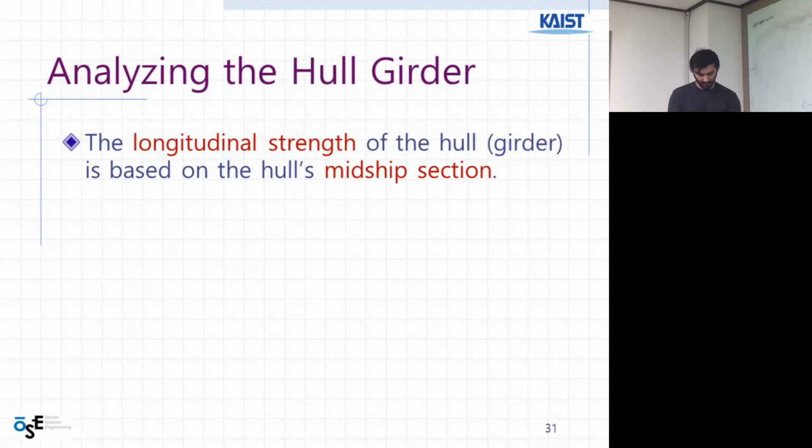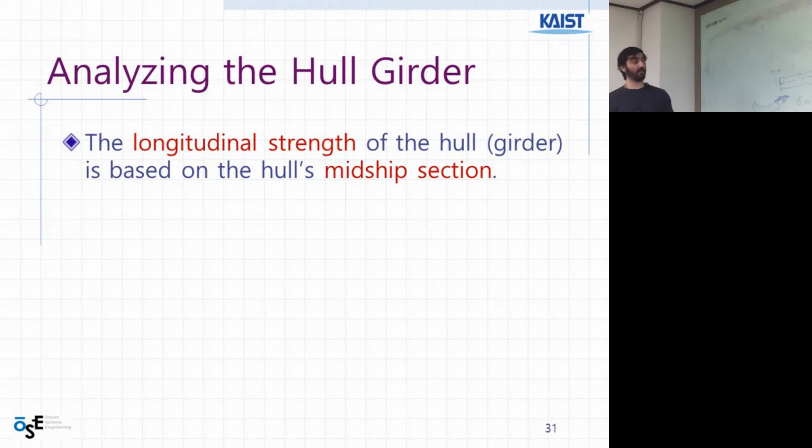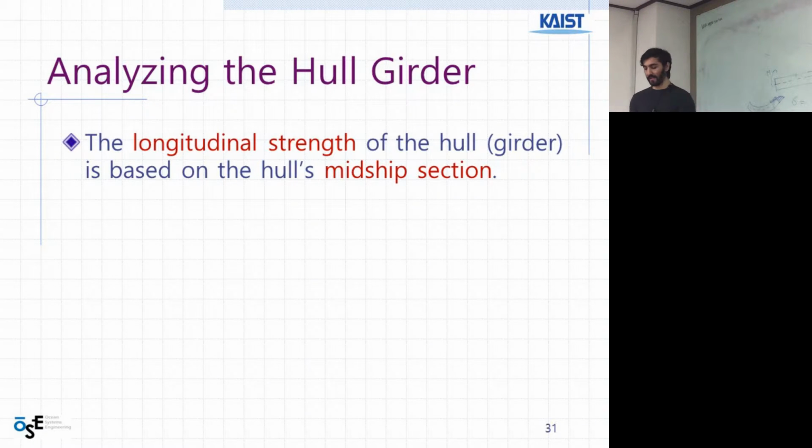A girder is a longitudinal member used in the construction of the bottom of the ship. It can be placed right above the keel, which is called the center girder, or to the sides, spaced equally from the keel, and then they are called side girders.